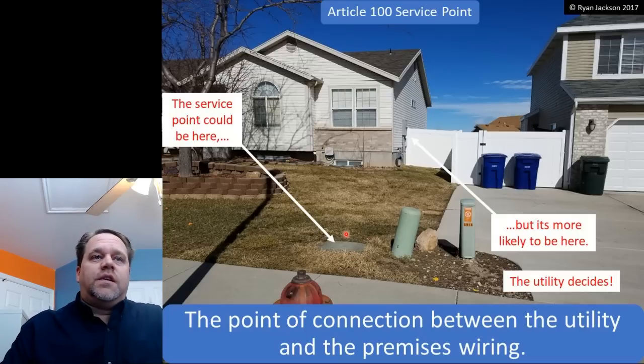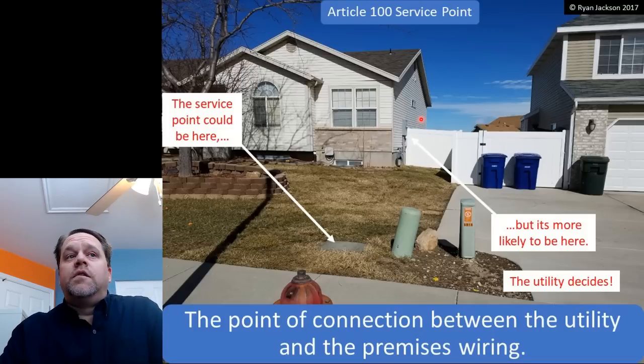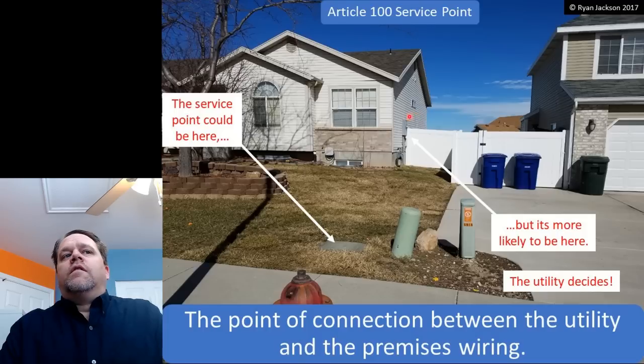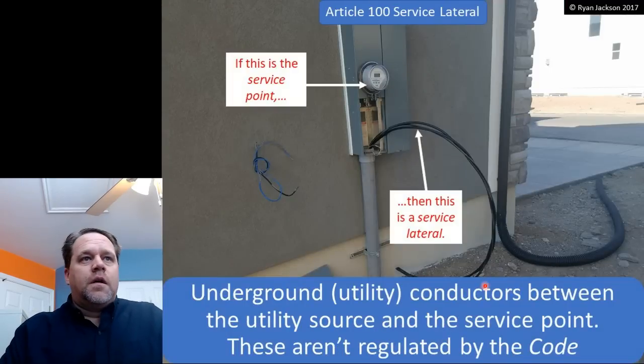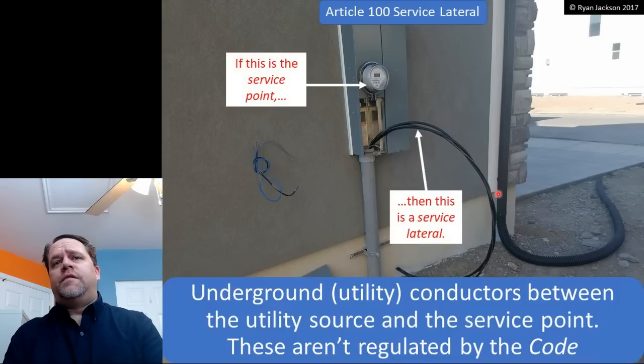Now, in this installation, it's more likely that the service point is at the meter socket enclosure at the house. Could be, might not be, but in this application, it probably is. So if the service point is at the meter, then the service lateral is the underground conductors from the utility source to the meter. Let's go back. These wires would then be a service lateral. If this is the service point, then that's a service lateral. And we know that service laterals are exempt from the NEC.